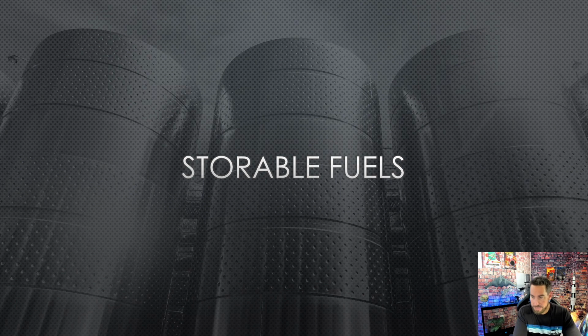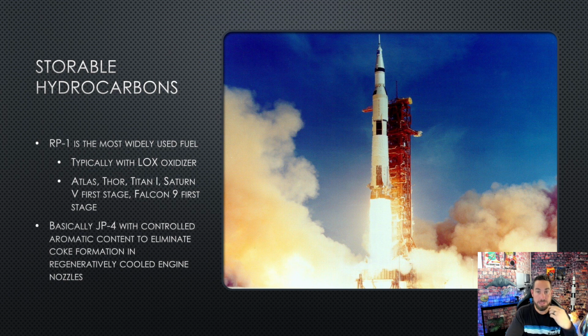All right. The final segment will be over storable fuels. There are only a few cryogenics, so liquid hydrogen and methane are the two big ones. So now let's look at the storables. Of the storables, RP1, a kerosene derivative, is the most widely used rocket fuel. Typically it's used with a liquid oxygen oxidizer. So Atlas missiles, Thor, Titan 1, Saturn V. This is the Apollo 11 mission. It used RP1 mixed with liquid oxygen, ignites, and this is what you see right here.